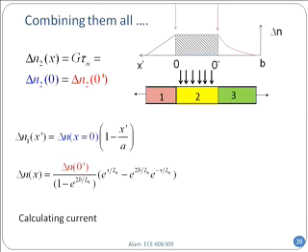Okay, now do you see it looks like some sort of bridge. Look in the middle, but look at this is the carrier concentration. In the middle, uniform light shining. So what is the value of delta n in the middle section? G multiplied by tau sub n, right? A certain rate it is being created and it's recombining at the same rate. And so steady state is G tau sub n. And on the left hand side, trap free going to the metal contact, it is getting linearly to 0.